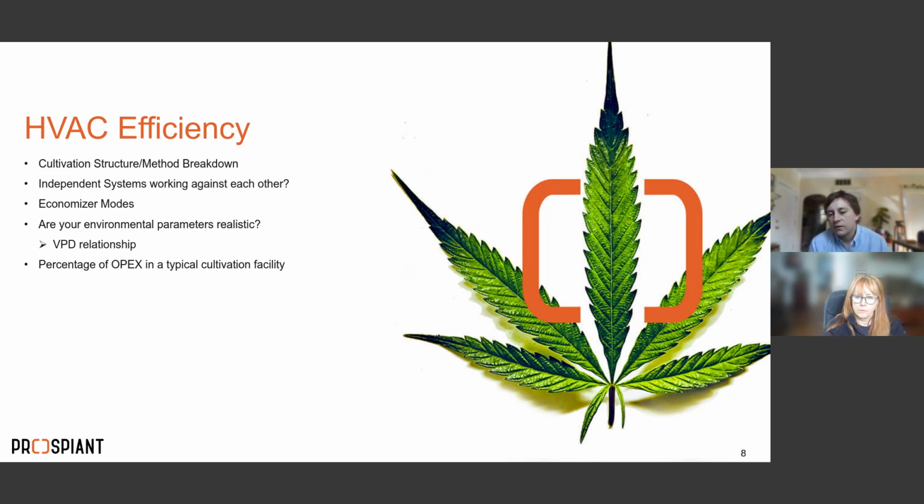on economizer mode? In economizer mode, what we would kind of call that is if you're growing in the Midwest and it's the middle of the winter time, and all you have to really do to utilize that outdoor air is heat it up before you put it in the zone. You don't have to do any dehumidification. Are you able to pull directly from outdoor air instead of indoor air and just heat that up for a third of the price that it would be to bring indoor air that's too hot and too humid, take both of those out, and then reintroduce it? Can you just pull that outdoor air, heat it up, enter it into the zone, and it's perfect?